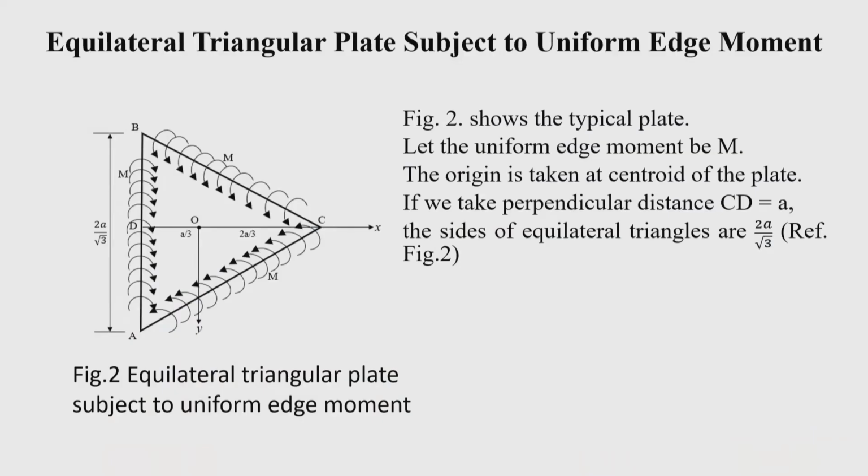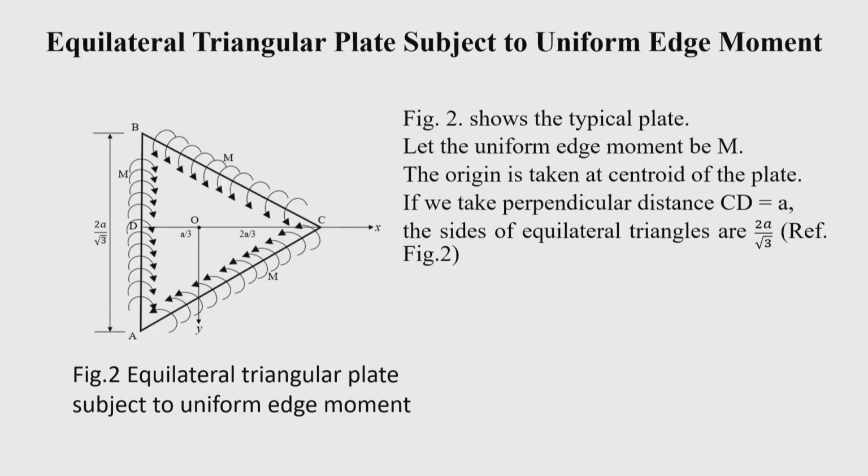Now, I shall discuss another problem that is sometimes encountered, and you can see how we have developed the solution. The solution is developed by taking a deflection function, or assuming a deflection function reasonably, that can satisfy the boundary conditions. Okay. Now, here the problem is a triangular plate, but for simplicity I have taken an equilateral triangle. So, each angle of the triangle is 60 degrees.